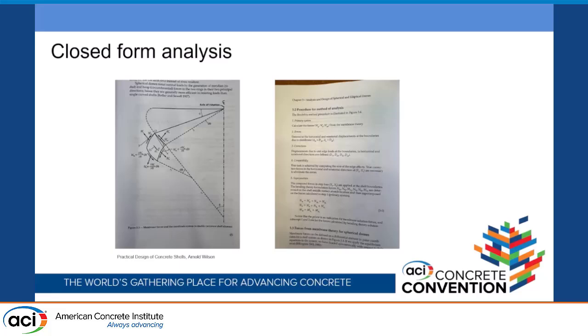So your errors are edge conditions, edge constraints, deflections, and you analyze it for those errors. Then you have compatibility, or you have to resolve those errors, so you have some external forces that you apply to resolve them. And then you basically superimpose all of those different analyses together, and that gives you all of the different bending forces and the axial tension and the axial compression.